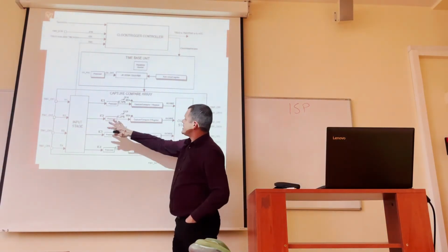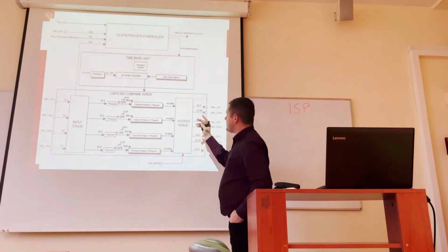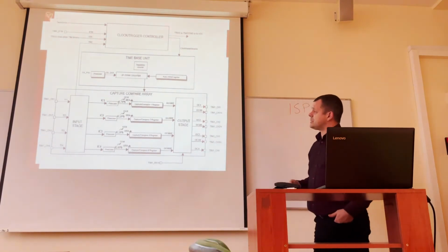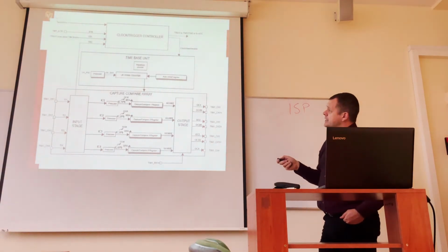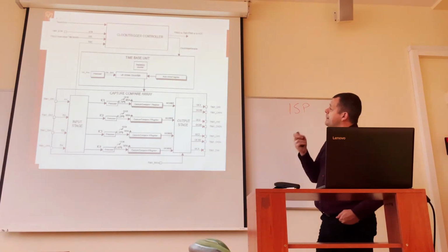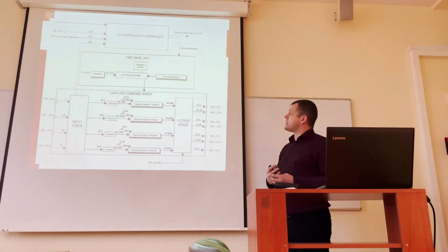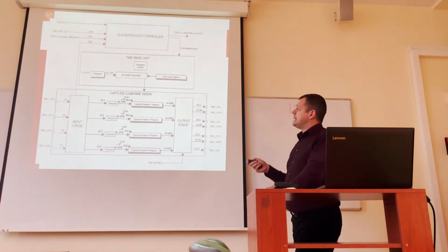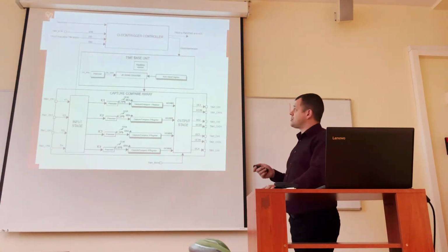Besides this, an important thing is the structure. That's how it looks inside. That's for Timer 1; the other timers have it simplified. So we have normally in timers the time-base unit, where the main clock, which is incoming to the timer, goes through the pre-scaler and then is counted by the counter. Timer 1 is an up-down counter, but in case of the simpler timers, we've got just the up-counting functionality.